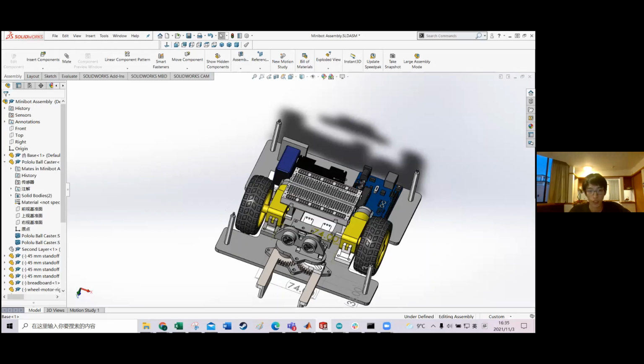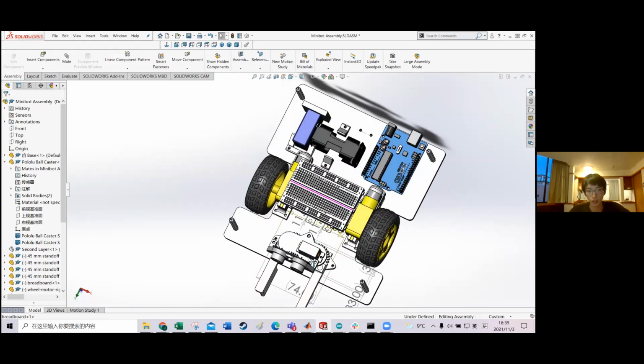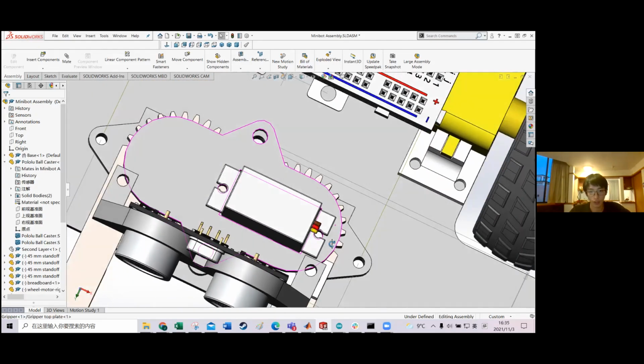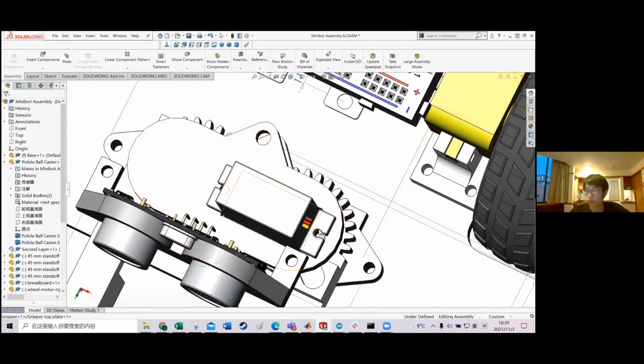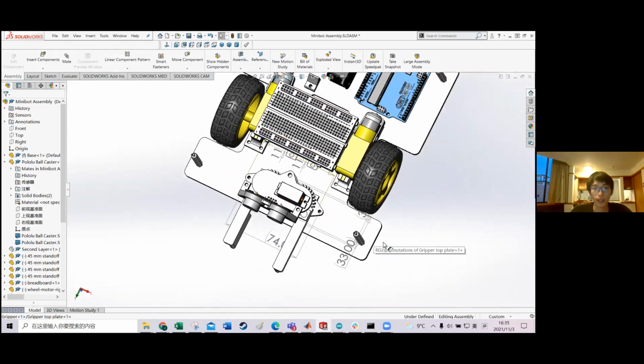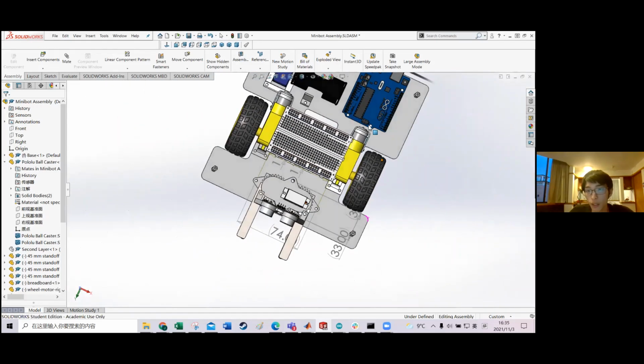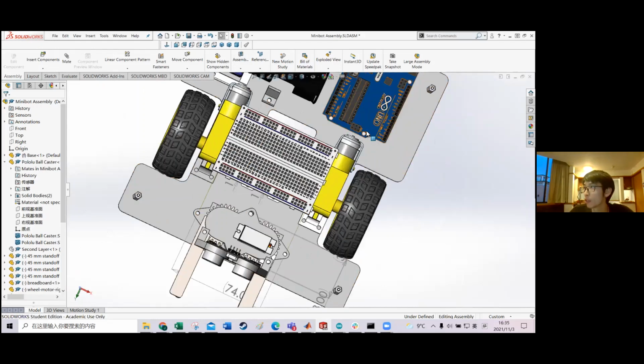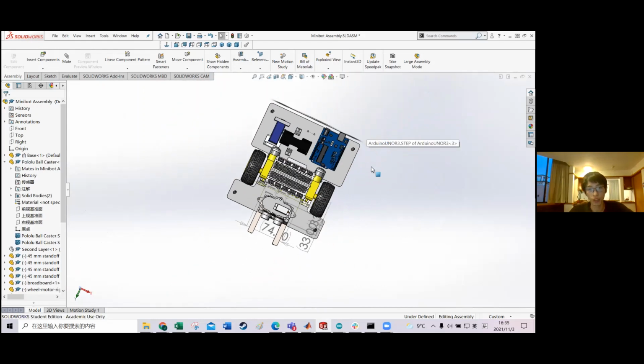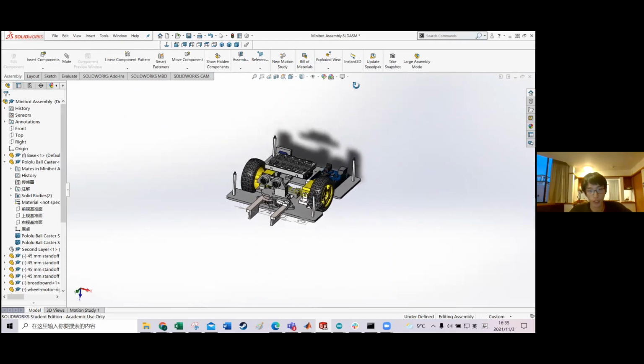That's just one of the standard sizes. And for the motor, just here, slightly smaller, because the hole on the servo, sorry, is slightly smaller. So we use M2 for that. And I think that's it. Even the mount holes on the Arduino are M3. So most of them are just designed as M3s.